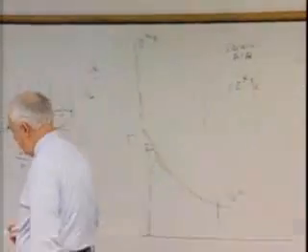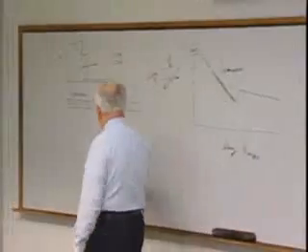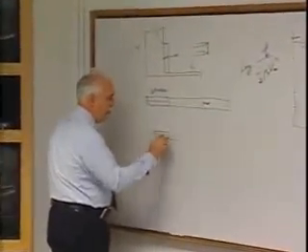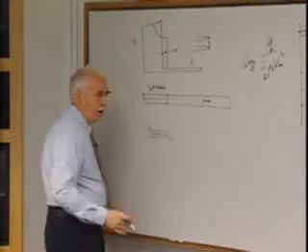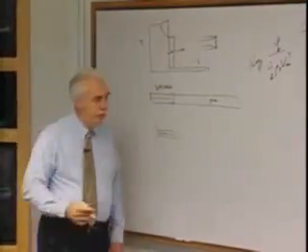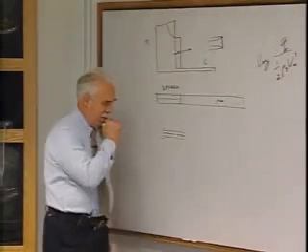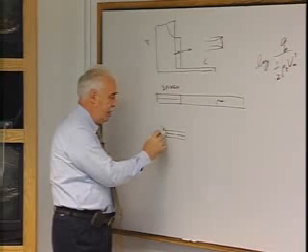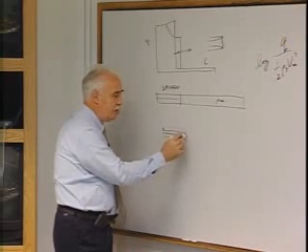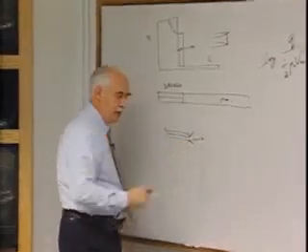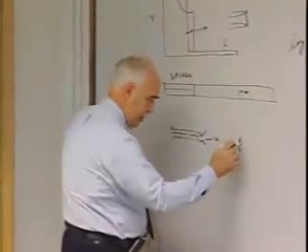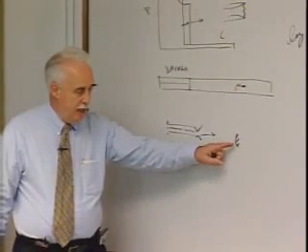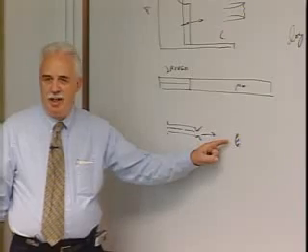Now, an arc jet is a continuous electrical discharge, sort of like the shock tube, where you're discharging an arc along a tube about the length of these tables, of a very high current, continuous for a significant period of time, into nitrogen, and then you're expanding this and you're introducing a supersonic flow, and you test materials like the tiles or the ablator in as close to the environment as you can get on the ground.